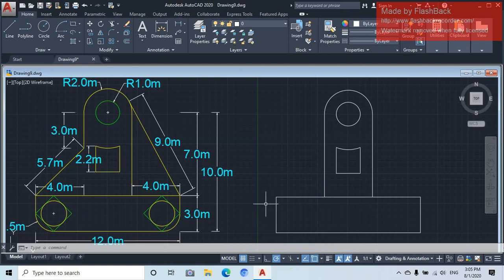So you activate 45. Now we go back to the line command, you click here at the midpoint, you left click and then you move it upwards, and you're gonna see this green polar tracking line, the green polar tracking axis line.